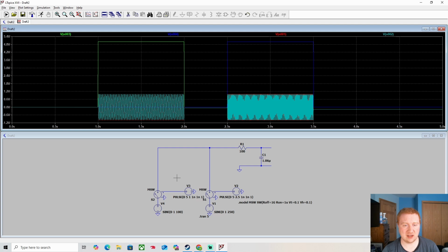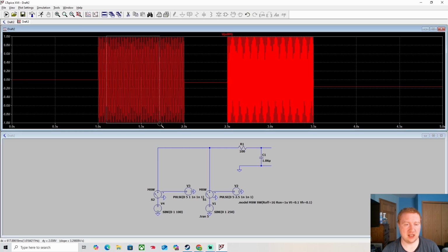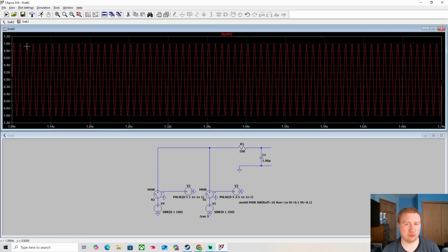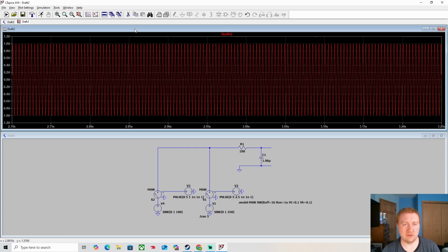So at about 1 second, for 1 second, it stays on. Yeah, 1 second in, we have a 100 hertz sine wave at 1 volt. And you can see that the amplitude is pretty much 1 volt. You can't really tell that there's any decrease here. At 250 hertz, again, it's going to be very close to the 1 volt. It's technically a little bit less.